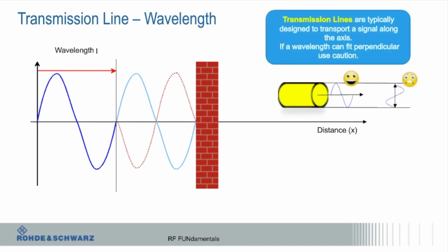Okay. They're typically designed to transport a signal along an axis, right? One thing, just a cautionary note, often you need to turn when you're using a cable or a transmission line. Avoid right angles. I've seen stuff where they actually measured current density on some instruments, and you'd be amazed how much things change when you take a sharp turn. It really degrades the performance a lot, so try to avoid that. Just think of it like flowing like a pipe, really.